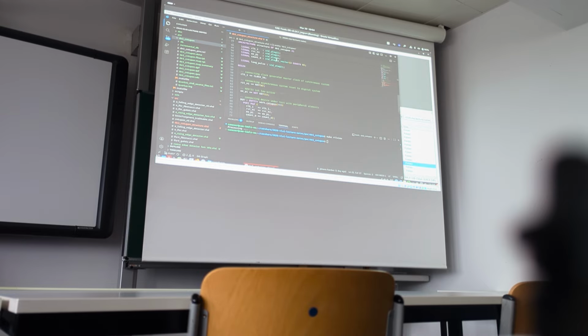Then we assign the different signals, the clock 50 megahertz to our clock signal, key 0 to our asynchronous reset, and the enable to key 1. We instantiate our device under test with the signals which provide our counter output, and this goes to our binary to 7 segment encoder.